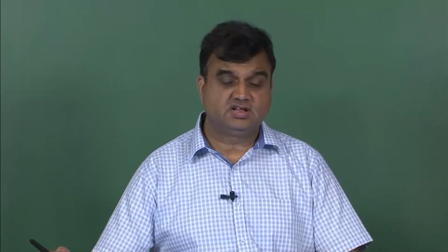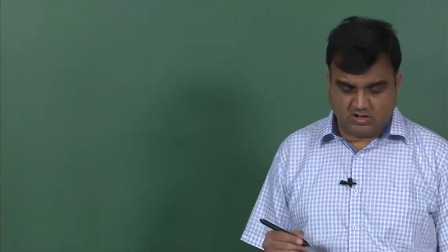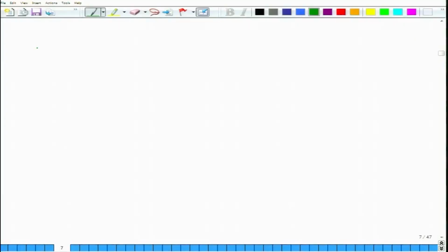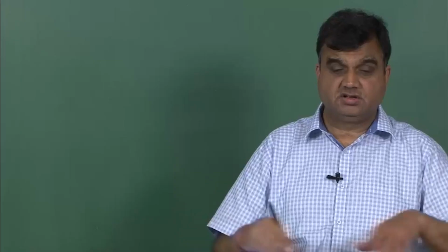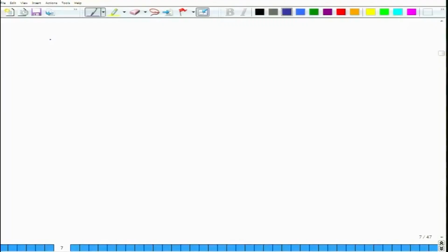Hello, welcome to Introduction to Composites. We started a new topic yesterday, and specifically what we started developing were strain displacement relations for composite laminates. What we had shown yesterday was that the displacement in a composite laminate at any location x, y, z can be expressed in terms of mid-plane displacements and mid-plane curvatures. So, that is what we are going to re-express that as.